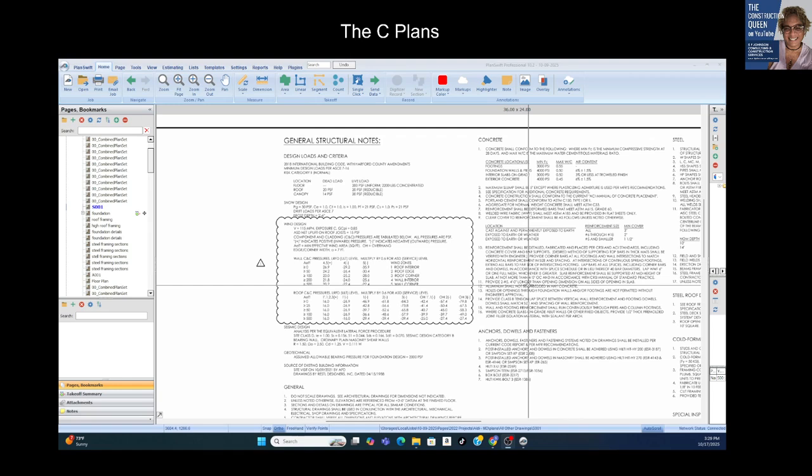And that's what window and door headers are for. Although you may see headers in the architectural set, they're really a part of the structural set. So you get three 2x4s plus something to fit the opening. Those are structural components. Okay, so vertical load path.